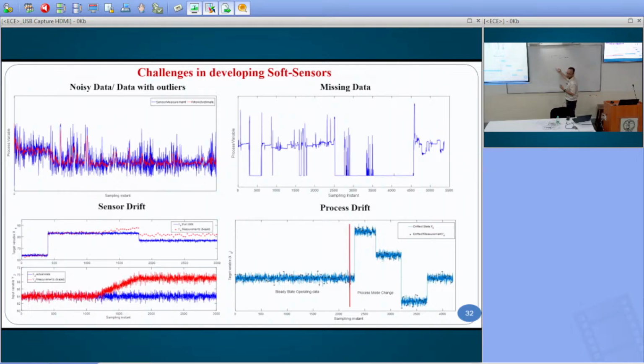So I add the error to the prediction, then immediately there will be a shift in my predictions. Then again you can come closer to it. After that, at a certain time again there will be a deviation. So whenever the new sample comes, I'll again add an error to it, then it will again push back. I keep updating this error as and when my measurement comes from the plant.